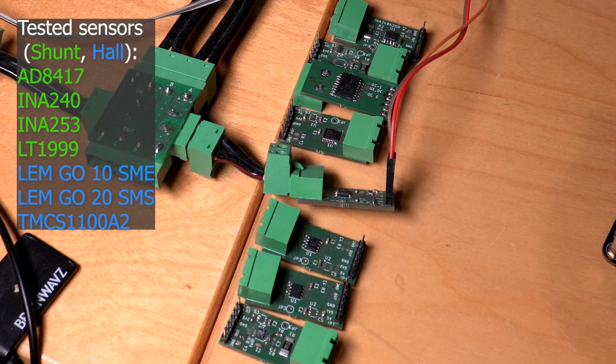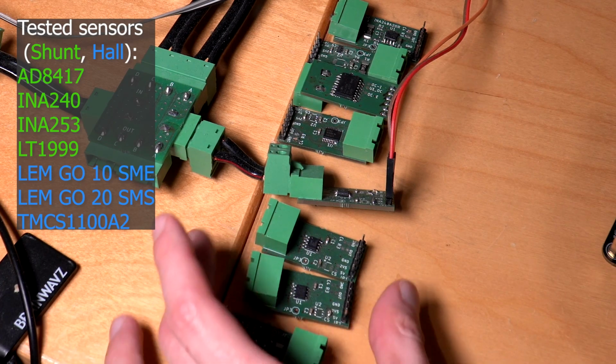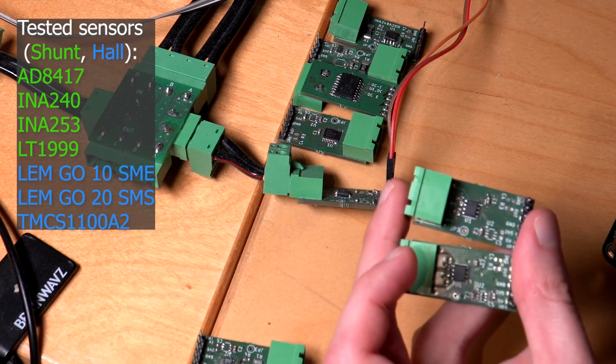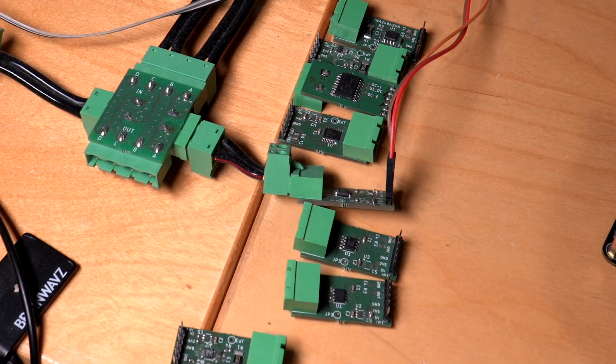I have tested some shunt-based solutions, but as we are dealing with high common mode voltages of up to 60 volts, I also wanted to try out some Hall sensors. The best performing Hall sensors I could find for this application were the LEM GO 10 SME and the TI TMCS1100A2. The LEM has very good external field rejection, but I was unfortunately only able to get enough samples from the manufacturer for my experiments.